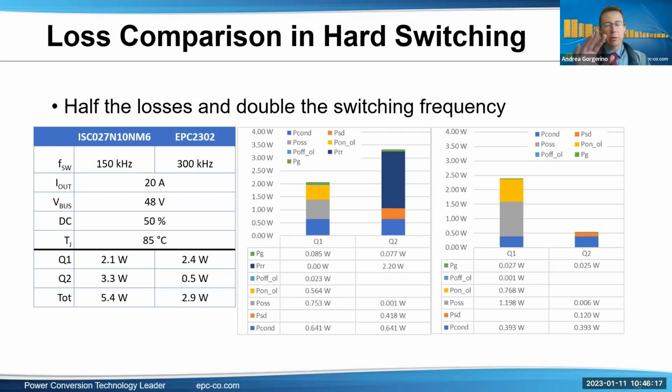It depends on the part. The temperature coefficient is slightly different for RDS on, but usually slightly lower, but very similar. The threshold also has a temperature coefficient. Silicon FETs have a quite negative temperature coefficient, which means it gets lower with higher temperature. GaN FETs have much more stable threshold, so it's almost constant over temperature, which is a better behavior, I would say. But that's all I can say. I'm not sure I fully understand the question.